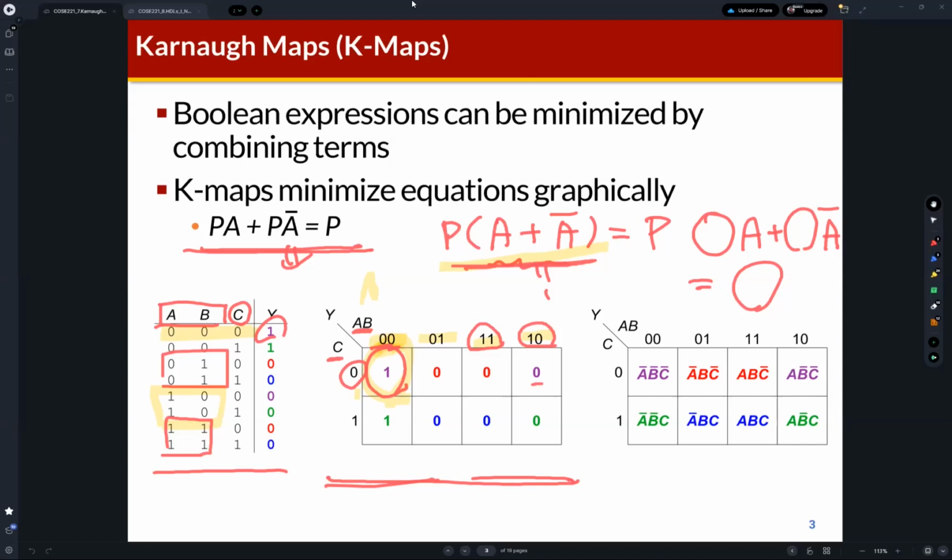Okay. And then based on the truth table, I said that we can generate a Boolean equation, but these Boolean equations are not optimized. So in order to generate the optimized circuit, we need to minimize the number of gates, right? Because in order to implement a digital gate, we need to invest transistors. Those are hardware resources. So using the Karnaugh map, we can optimize the Boolean equation.